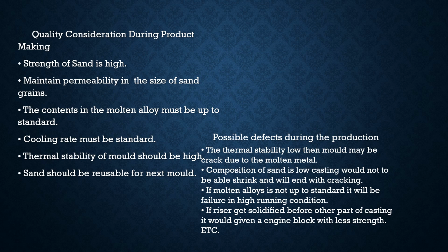Possible defects during the production. If the thermal stability is low, then the mold may crack due to the molten metal. If the composition of sand is low costing, it would not be able to shrink or will end with cracking. If molten alloy is not up to standard, it will fail in high running conditions. If the riser gets solidified before other parts of the casting, it would give an engine block with less strength, etc.